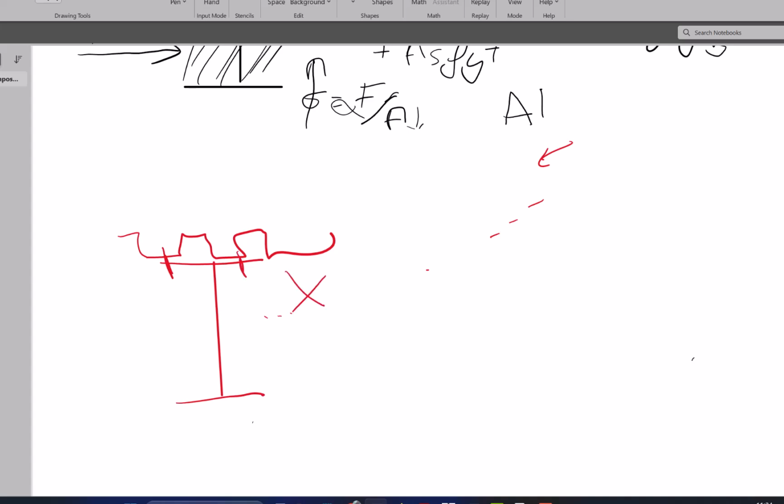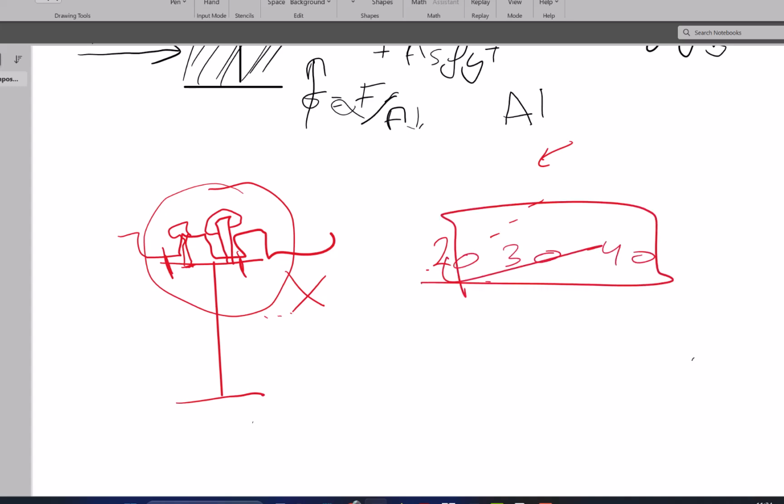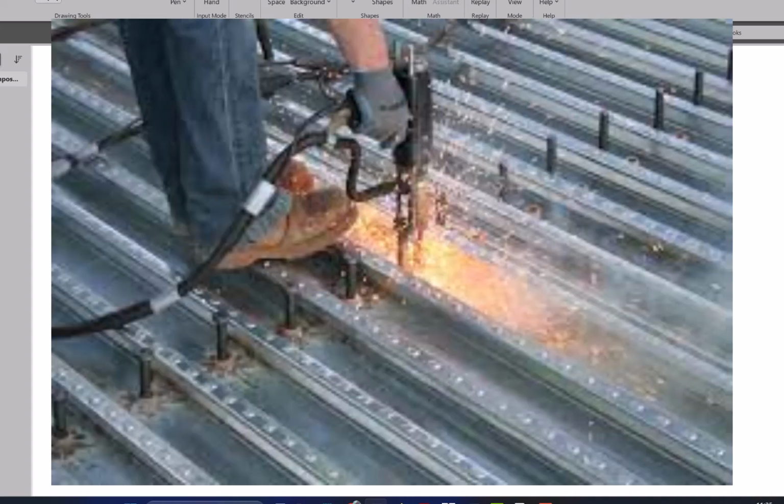If you think you can just weld a bolt here with manual welding, that again is very difficult to achieve. It has a very low value of composite action. For these kinds of welded bolts, what is the percentage of composite, 20 or 30 or 40? It's difficult to determine. Well, there are some guidelines on this, but the real way of doing this is welding the shear connectors to the beam. Here are some pictures that show you the type of composite beams that matter.